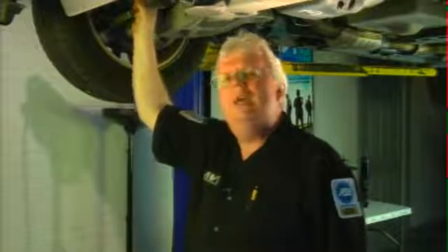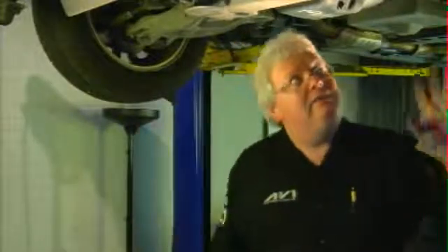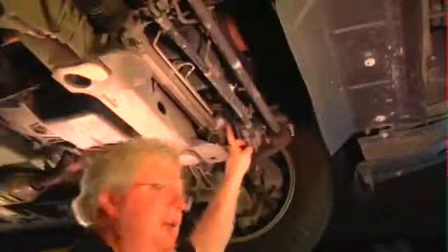Always check the boot itself for signs of cracking or splits, and also grab the tie rod end and move it up and down. That's going to be a test question, though. That's not really a scientific way of determining if it's loose enough to replace or not, but at least it gives you a ballpark whether to get the tool out, we're going to describe next, and do some measurements on it. Now, as I'm looking and inspecting this particular rack and pinion on this Lincoln, I see a connector right here that goes to the Variable Assist Power Steering System, VAPS, that Ford calls it.